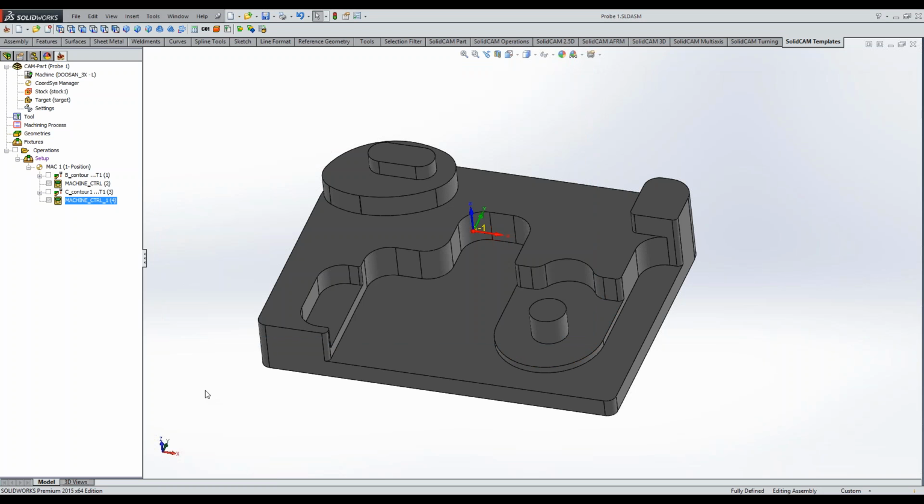So, that's it. Maybe we have any questions? We have one question here, actually, and I think I know the answer, but I'll let you answer it better. The question is as follows: can you only probe the original stock or the final finished component? For example, can you probe a semi-finished part in order to set the precise tool radius offset to maintain accuracy? Of course, but again, this is an option that depends on the cycle.